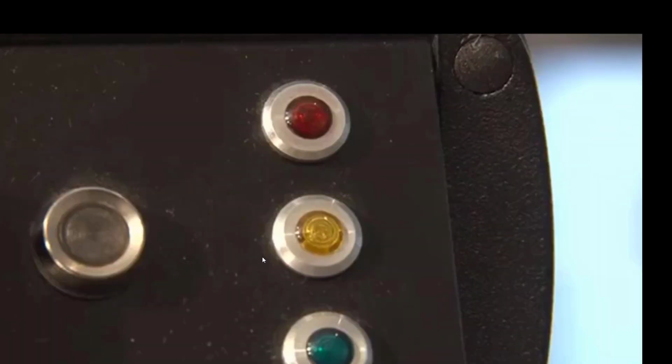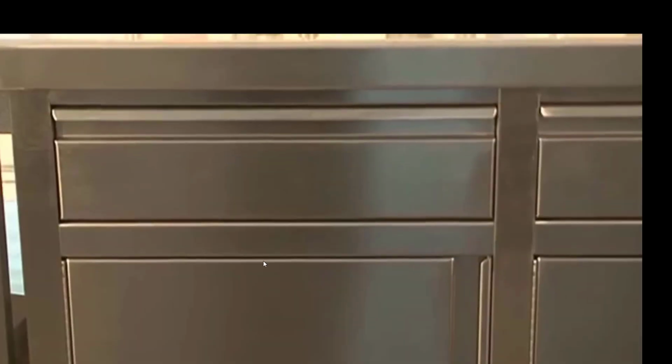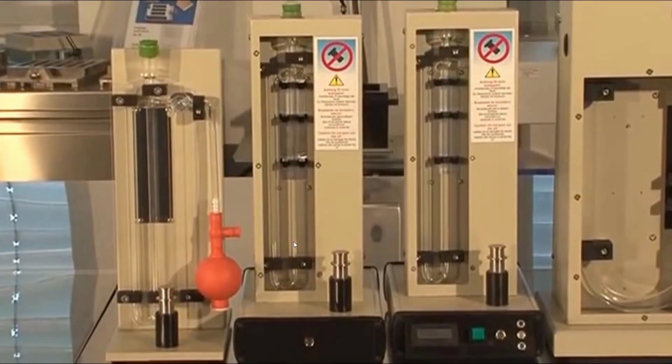In this experiment, first you will have to calibrate your equipment using some standard powder, so that you can find the K value of your apparatus, that is a constant value. Basically, K value is the ratio between the standard specific area and your specimen specific area, so that it can give an accuracy regarding this test. This is an automated Blaine air permeability apparatus, which is used to record the time automatically between the columns of a manometer.